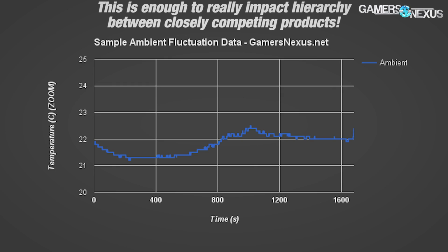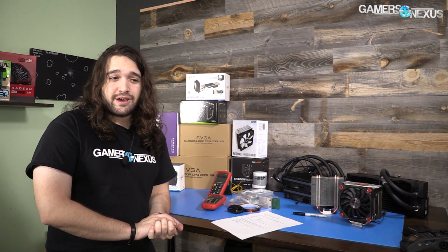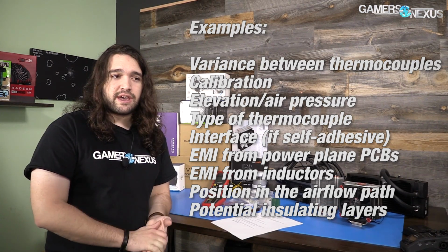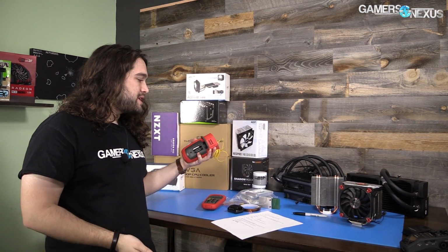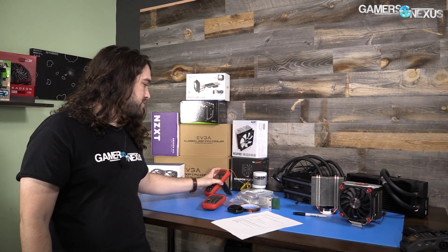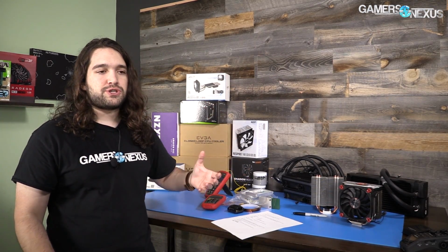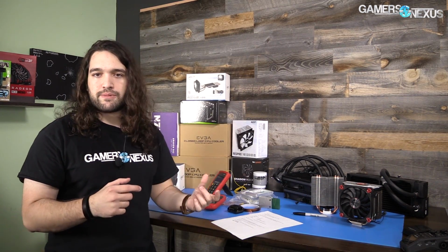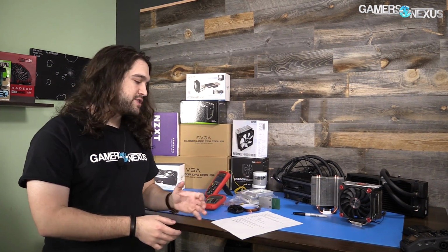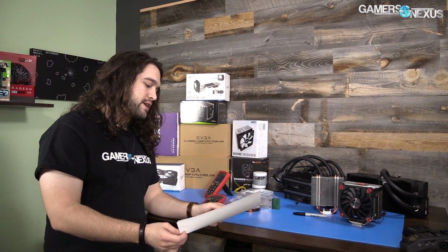And there are plenty of things there that are not quite so straightforward either, but we did discuss that in one of our previous videos. I'll put it in the description or something. So thermocouple readers help. We use K-types. They have about a 2.2 degrees Celsius range. If you're using multiples, you will want to calibrate them. Put it in ice water, put it in boiling water, see what the temperature difference is, and then you create an offset in the spreadsheet and just build a template around that.